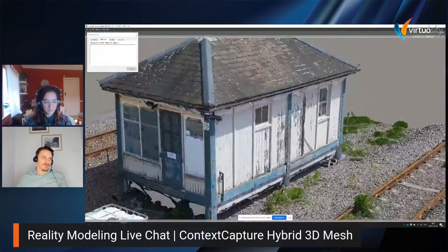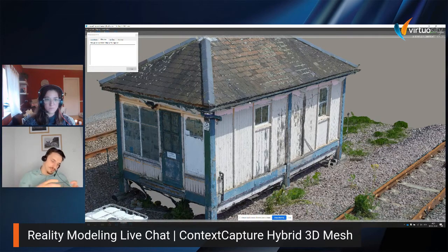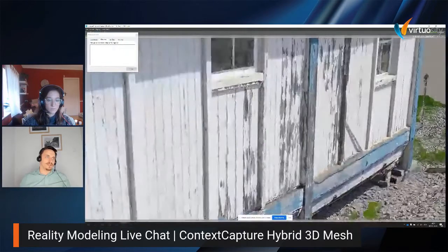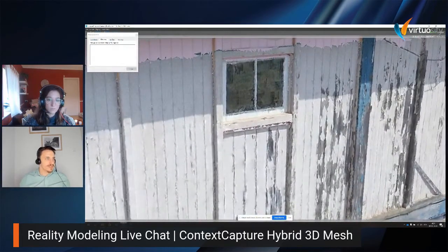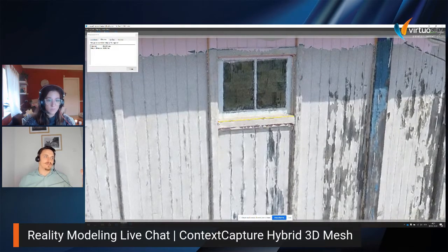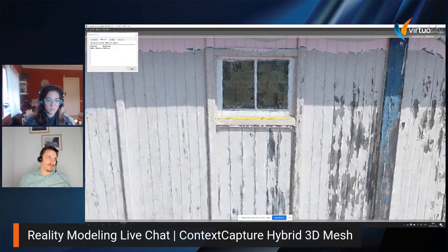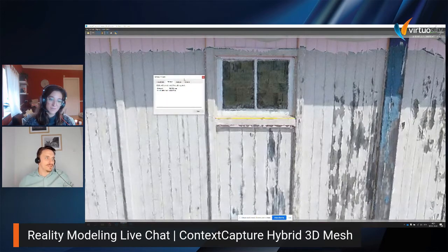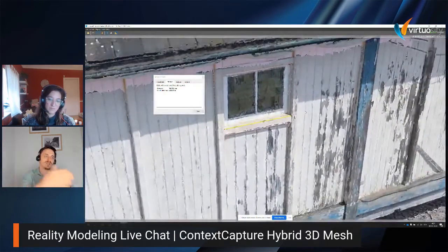A 3D mesh, when we are delivering it, doesn't have that much hazard and chance of misclicked information as the point cloud had. On the point cloud, the customer had to use sections or different techniques to get the best view to measure something. But here, if I would like to measure any distance, the chance that I'm going to click a point which is behind, for example, this window here is really small. It's impossible, in fact, because this is a continuous representation, so we have everything covered here. In the case of a point cloud, I would have a chance that I'm going to click this window, but also a chance that the point I'm trying to choose is going to be a point behind, on a different wall. So right here we are getting really good results just by clicking, and that's why this is much easier for the customer to use.